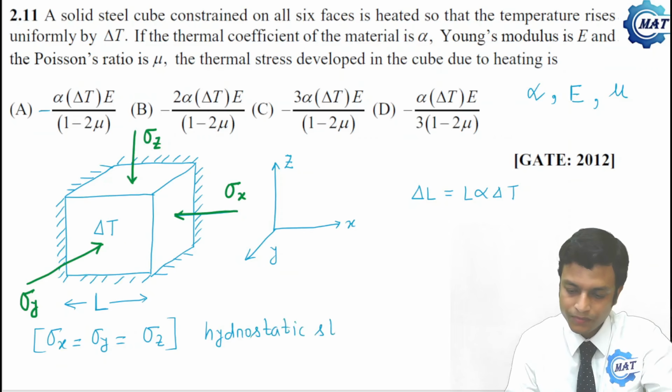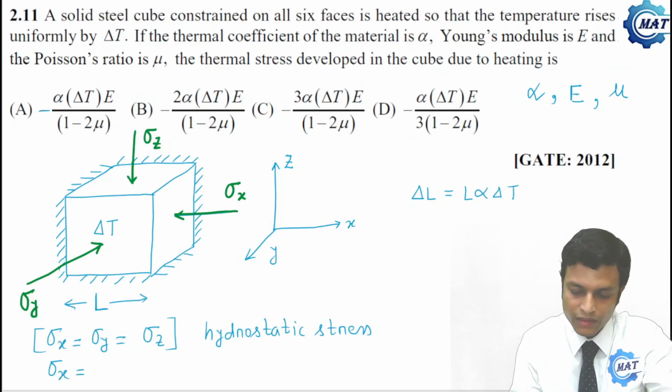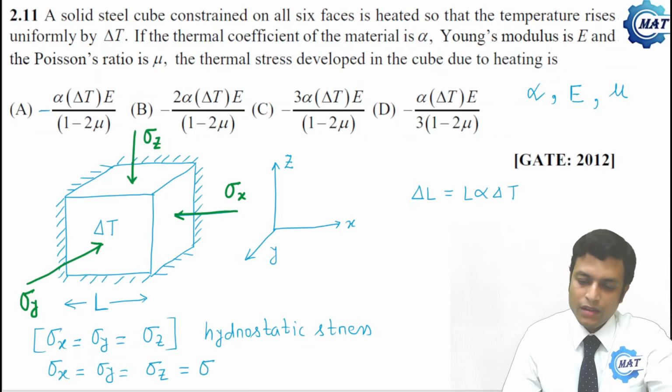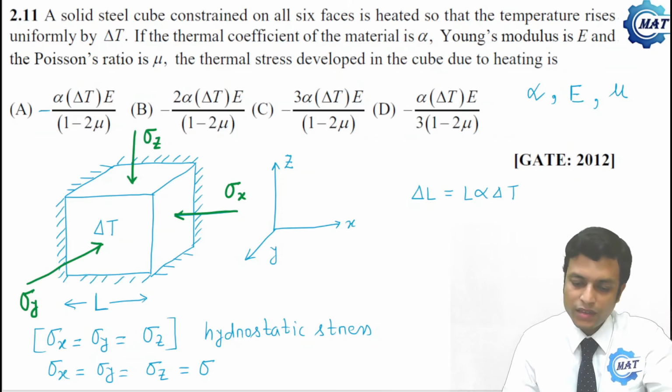We can consider that sigma X is equal to sigma Y equal to sigma Z, and that is equal to sigma. Now we have to calculate what is sigma, that is the thermal stress developed inside the cube.